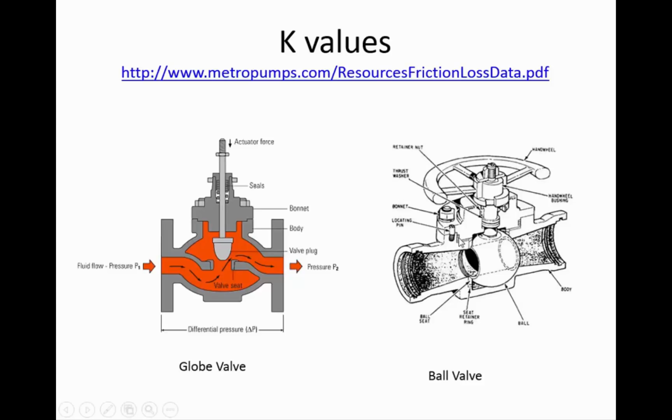A ball valve is really easy to open and close. What you're essentially doing is you've got a pipe section drilled through a sphere, and when you turn the top handle here, you're just moving that hollowed-out pipe section from the sphere out of the flow direction, so that the water that's coming in is just running into the leftover metal or plastic in that ball valve. But it can leak around the sides. Water at really high pressures can easily leak around the side of the ball, so it wouldn't be a really great option if you have high pressure coming through the flow.